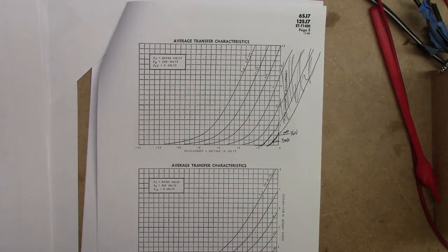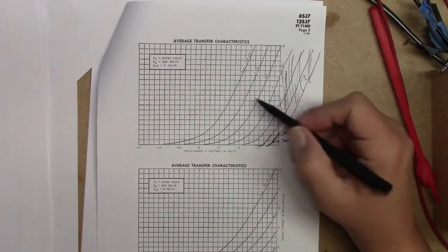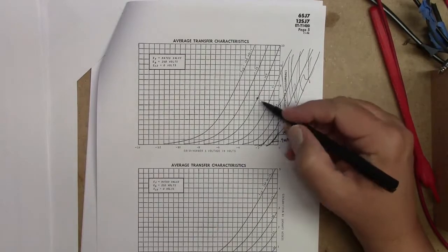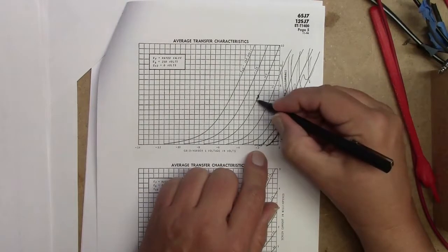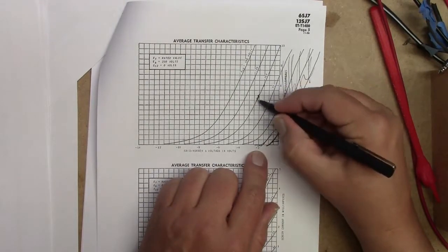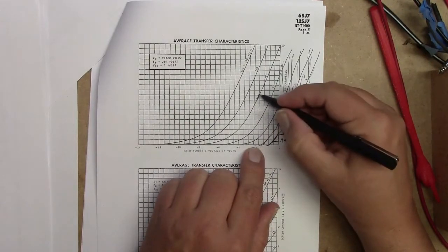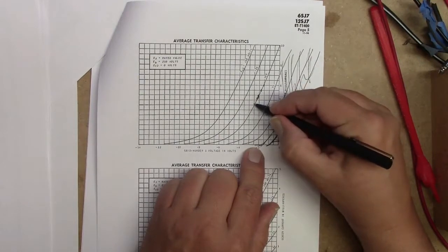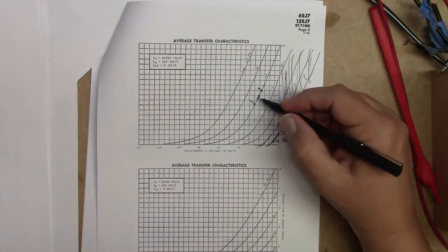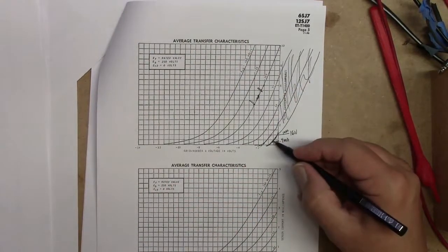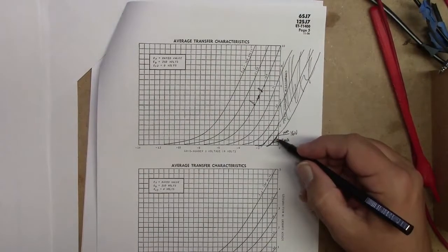If I have a 500 millivolt signal coming out of the guitar, and say I pick a value over here somewhere, let's say I pick right here, and we get, on the right, 2 volts, 500 millivolts will swing to here, down to, well, this is 3, yeah, so 500 will be 250. So we'll be swinging about here, which is a pretty straight line. If we take that same 500 millivolts and we run it across this one, this line is really curvy right here, and this is going to lead to distortion, which is kind of what you want, but we'll talk about that next time.